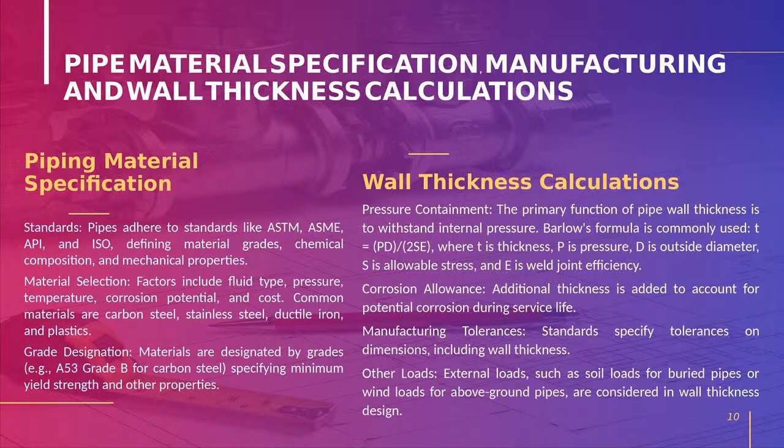While procuring any product related to piping, we have to refer to this PMS, and then we have to check the quality of the product along with this PMS only. In this PMS, everything will be shown. There will be a piping code, a piping index number, for each and every pipeline.